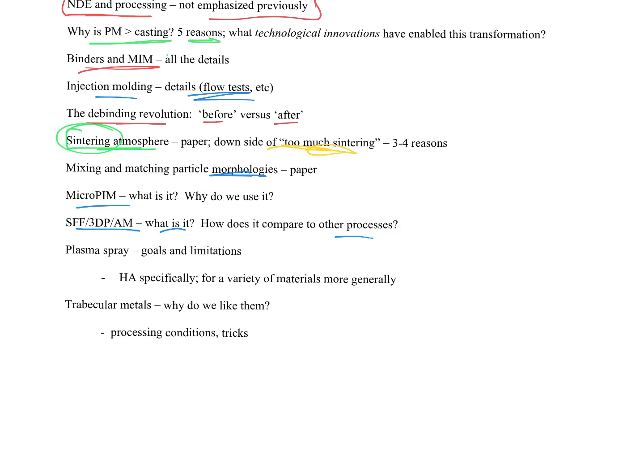So we know that, of course, making plastics by 3D printing or additive manufacturing is pretty straightforward. But in the context of making these complex biomedical alloys, it's a lot tougher. It's a lot more difficult to deal with. We still have issues associated with this, like MIM, that relate to what happens with additive manufacturing, because we still have binders that need to be removed. All those things are going to be important to us, and we have to try to transform a collection of particles, because we're still dealing with particles even though they are printed, into a microstructure, which is not anywhere near as easy as it is for plastics.